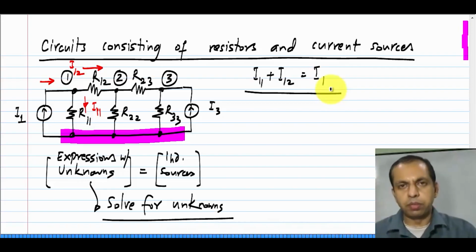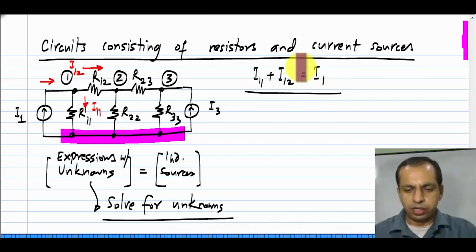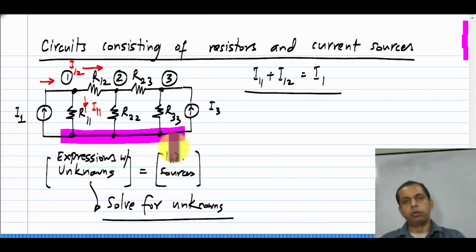Now, I have to choose some variables to solve for. Like I said, while doing nodal analysis, I will start off with KCL equations, but while writing down the terms of the equations, I will be implicitly using Kirchhoff's voltage law as well as the element relationships, in this particular case the VI relationship of a resistor.